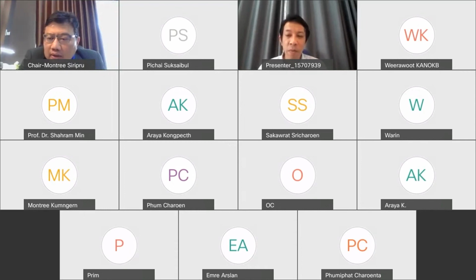I think because the circuit consists of the BJT. That is the main point giving the cut off frequency lower than the CMOS. And for question 2, the power consumption is 2 times larger because this circuit uses many current sources to bias the circuit. That means the circuit is consuming more power than the CMOS structure.